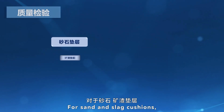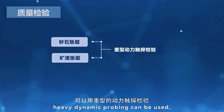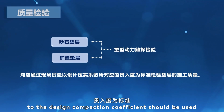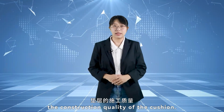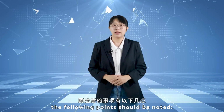For sand and slag cushions, heavy dynamic probing can be used, and on-site tests should be conducted. The penetration depth corresponding to the design compaction coefficient should be used as the standard to inspect the construction quality of the cushion. When conducting quality inspections, the following points should be noted.